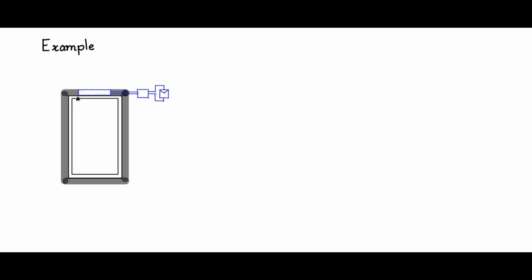Now this portion will be the cold portion, and that will be the hot portion of the Peltier element. On top of the hot portion, I will place a heat sink. I will just place a block of aluminum. Because this is a cylindrical box, I will take a cylindrical shaped block and place it on top of the hot plate of the Peltier element in this fashion. So this is the aluminum block which will act like a heat sink. It will remove the heat from the hot side of the Peltier junction and put it out into the external ambient.